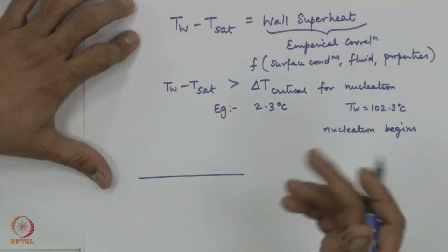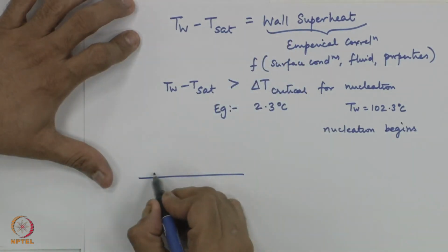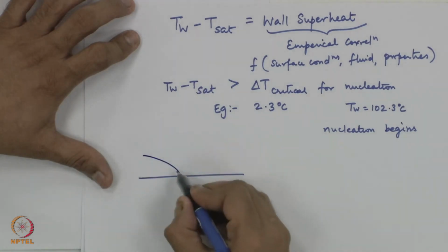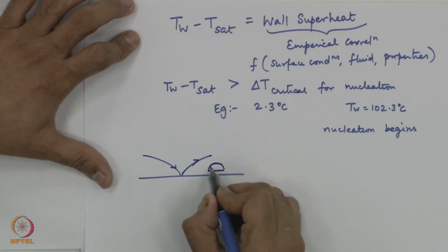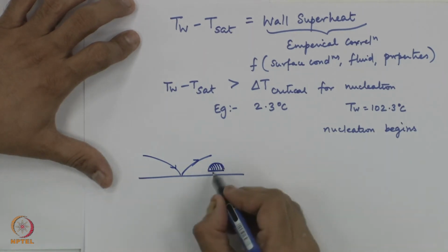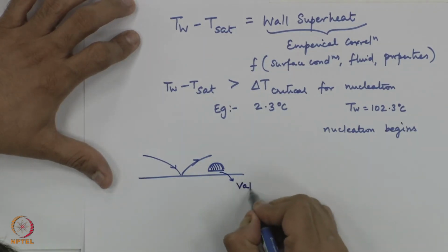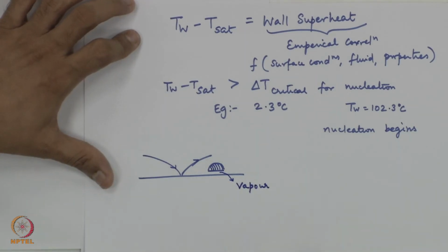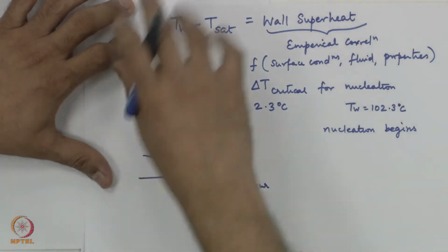It depends on the temperature of the heated surface. When the pan is very, very hot, let us say instead of batter, droplets, the water which the person sprinkles on the pan, the liquid is not able to come in contact with the heated surface, it will just bounce from the surface. This droplet would stay above the surface, because the moment the liquid comes in contact with the heated surface, vapor gets generated because of this very high temperature, and this vapor will form a cushion between the heated surface and the liquid droplets, and therefore you would see these droplets dancing all over the surface.